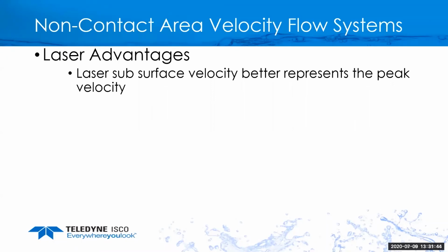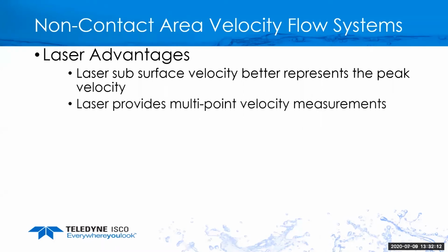So if your hydraulics are good, everything's moving in the right direction, pretty much any of them will work pretty well. If you have less than ideal hydraulics, I have very slow velocity, I have no surface turbulence, or I'm in an outdoor application where maybe the water on the top is getting blown by the wind one direction, but the water below it is actually going the other direction, laser subsurface is going to have a better chance of finding that peak velocity for you.